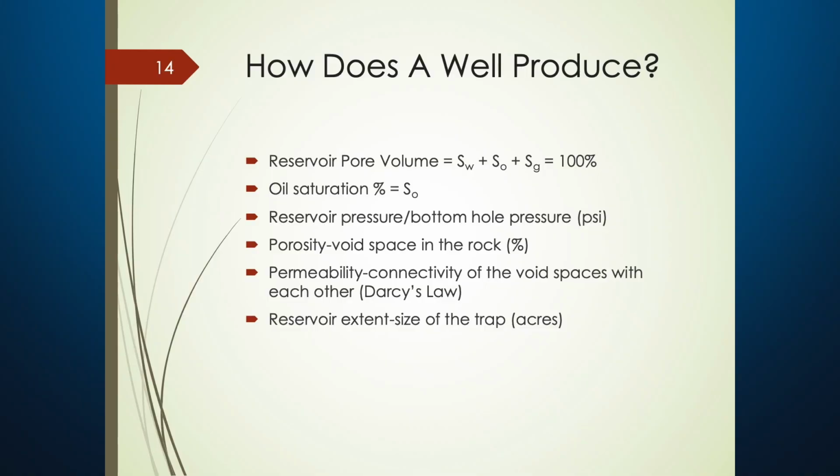So what does it take for a well to produce? Gary and Dale and all those guys, Jeff Hoy, they come in and they say, okay, this is the well. As an engineer, I'm interested in two things: how much oil is there, and how fast is it going to produce. So how do I know, as an engineer, how much oil is in that well? Well, we start out with this basic calculation right here. We have a pore volume. Remember we said there's porosity in the well. It may be 7%, it may be 15%, it may go as high as 22, 25%.